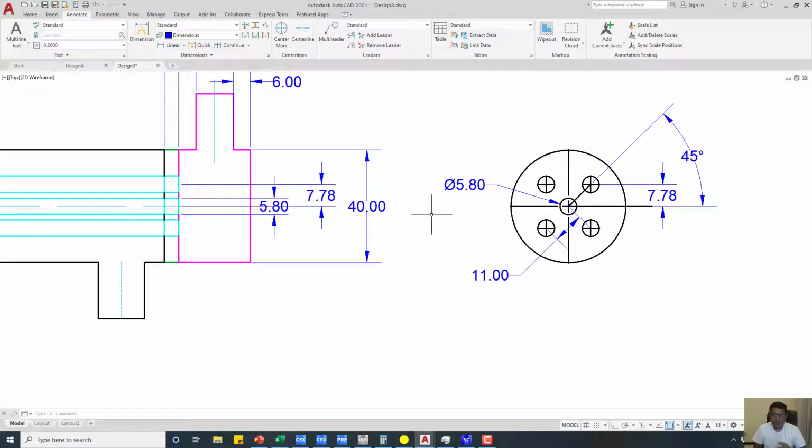For this video or this series, we want to compare two designs. One is when we have a single pipe, that is the pipe in pipe heat exchanger, and then when we have the equivalent size of the tubes, and then we want to see how this will affect heat transfer. And keep in mind that I didn't calculate the surface area of the single tube and these 5 tubes, but instead I proposed, based on the design, that we should go with the same cross section area which we get in the single tube.